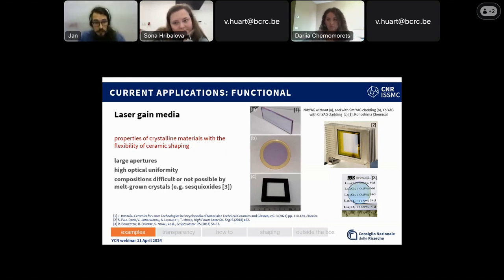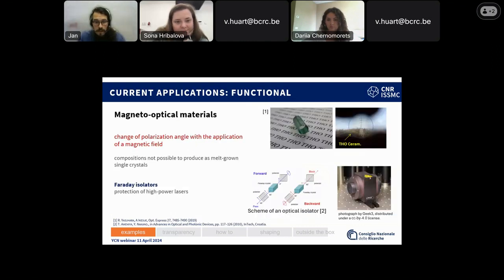And in the case of yttrium aluminum garnet, which is a composition that I've been playing with quite a lot, the typical sintering aid is silica, here added as an organic precursor. And you can quite clearly see on the microstructure itself that, okay, if I don't add any, here, for example, I have relatively small grains, but I have pores and the sample is just white, it's opaque.